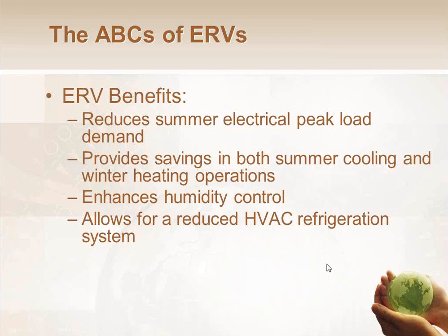In addition to the energy savings, there are going to be some other benefits of these systems. One is going to be reduced load on the compressors. I'm going to have smaller compressors on my HVAC equipment, hence a lower peak demand load. So not only will there be energy savings, there could actually be demand savings if your particular utility charges you demand charges. We're going to get savings both in the summertime and the wintertime operation. So this is not just one season or the other. This works in both seasons.